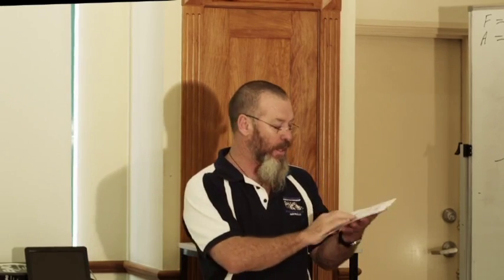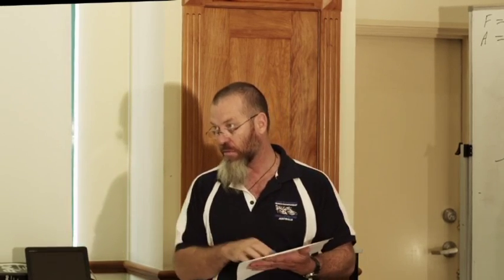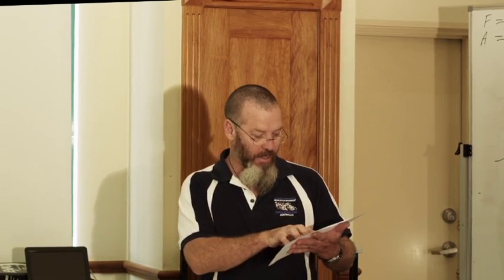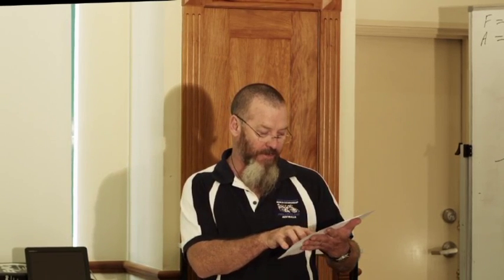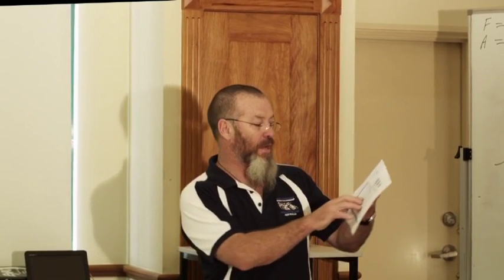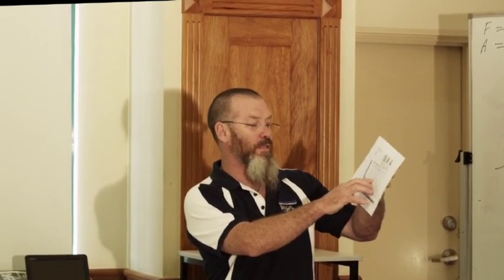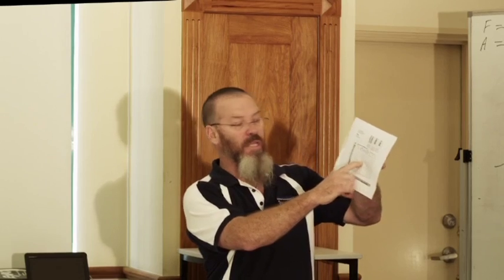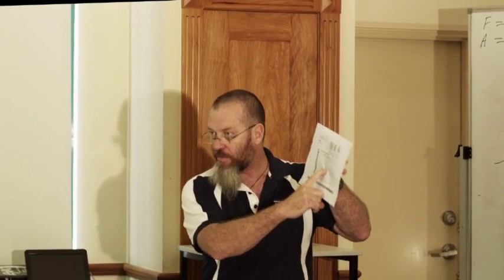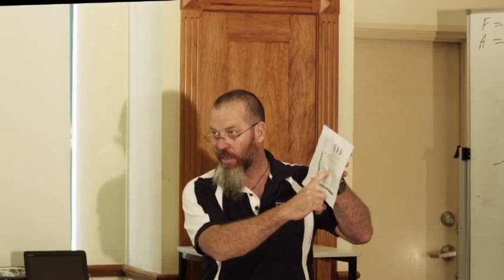Yeah, you got your head around that? 20 MPa concrete is the general strength of a slab. This one here says it will give you an uplift value of 6.1 kilonewtons of resistance. So they're good numbers. The only problem is, when you come back over here, it talks about minimum edge distance. So what it says is that you should be 70 millimetres in from the edge of the slab before you start the hole.